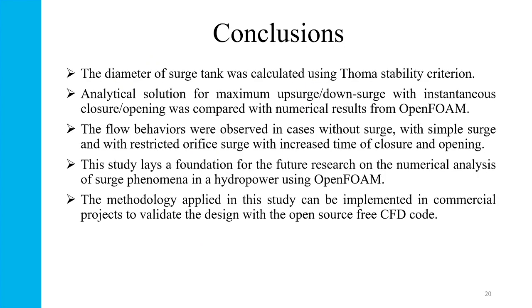Finally, in conclusion, in this paper we performed a numerical study of surge phenomena using open source CFD code OpenFOAM. The effect of using surge tank is studied with a simplified 3D geometry identical to a Nepalese hydropower plant. The diameter of surge tank was calculated using Thoma stability criterion and an analytical solution was obtained for the maximum possible upsurge or downsurge. The corresponding values obtained with numerical analysis in OpenFOAM were less than the analytical value due to the considerations of penstock length.